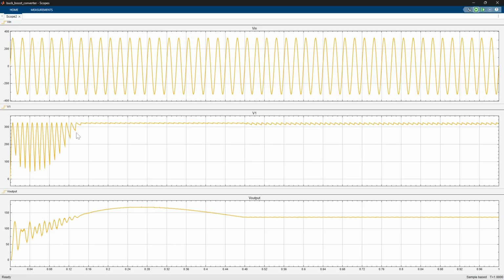At the startup region from around 0 to 0.12 seconds, the DC link capacitor starts uncharged, and it charges through the diode bridge. Each AC peak charges the capacitor higher. This causes a very large ripple, pulsating voltage, and this is a classic capacitor charging transient. It is unavoidable and 100% realistic.